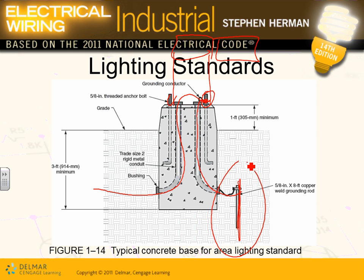So that's a foundation. This is all concrete foundation. You can see the depth of that concrete foundation. This is a good example, 1 foot elevation or even higher. It shows what you give the concrete people when you build this foundation for your poles, to go mount them, and then you bring the pole. If you're a contractor, this is a major thing, guys, because that's what you're going to be coordinating. You do the foundation for these poles, then you bring that pole, sit it on top of the bolts, and you bolt these poles, and you're done.